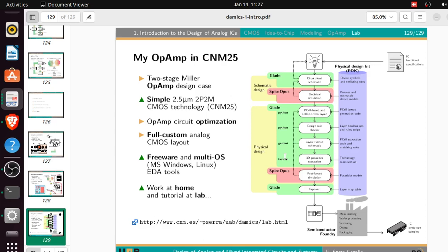You just want to make a MOSFET, but as part of what you're designing, you get capacitances and also resistance. From the device physics you understand why you have all those things. So for that given layout you've done, you get to see how much of those parasitics you have, and that way you know if what you've laid out is really going to work well.